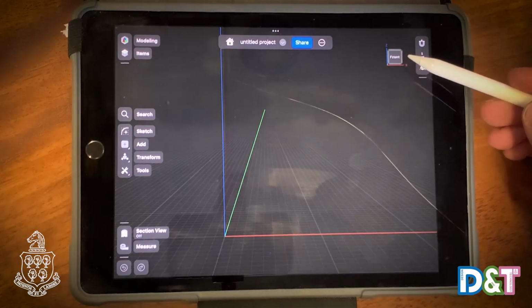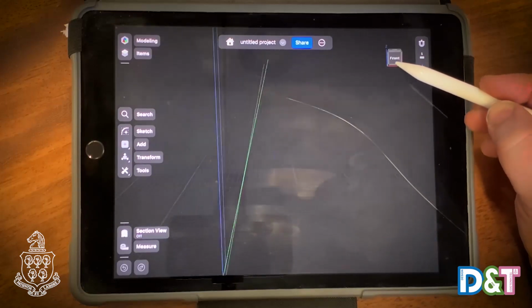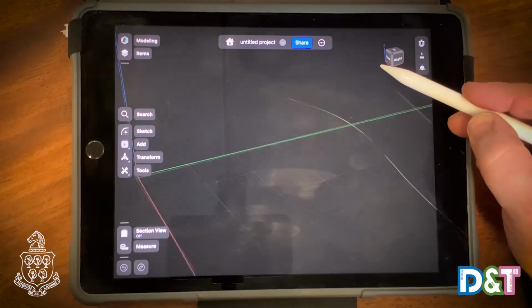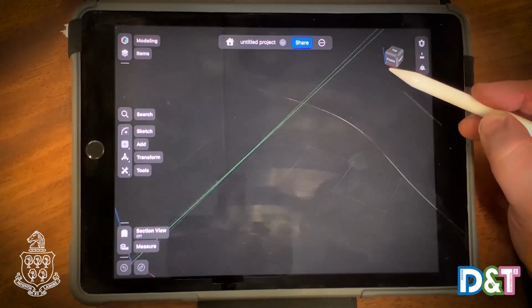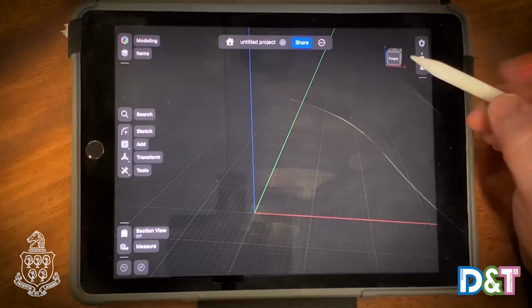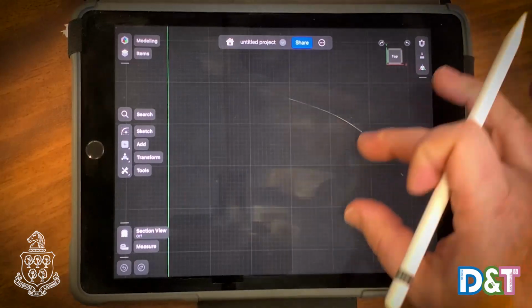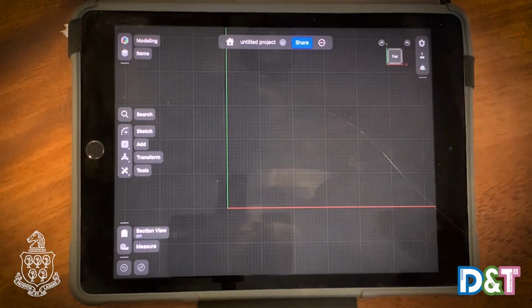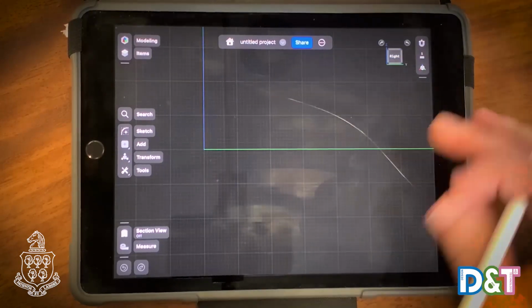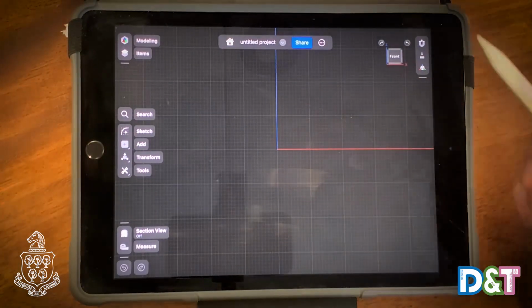In the top corner up here, there's a little cube, and if you click and hold down, you can basically rotate around your document, but you can see on the cube what the top is, the front, the bottom, the left and the right, and also the back. And so this is another really nice way of accessing different parts of your document. So say if I was to rotate it to see the top there, if I click now on the top side of that cube, it'll actually take me to a direct, straight top view. If I go to say the right-hand side over here and click right, it's exactly the same. So this is a really easy, nice way to navigate your document.